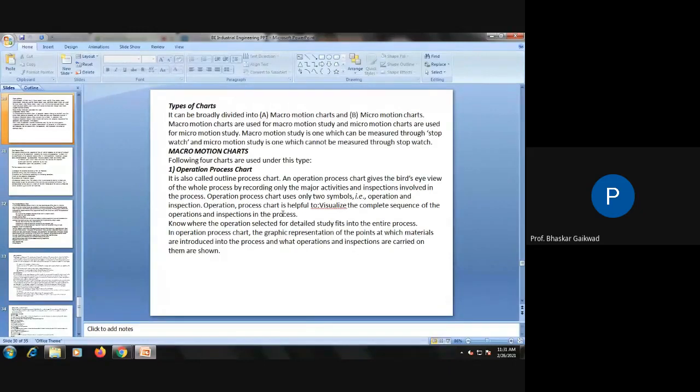So here we require a gauging system, to check whether the ball has been manufactured within the given tolerance or not. We can sort out the total balls by the gauging system, accepted balls on one side, rejected balls on the other. So the inspection becomes fast.